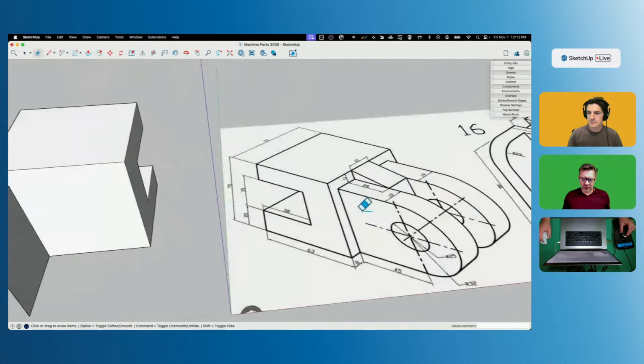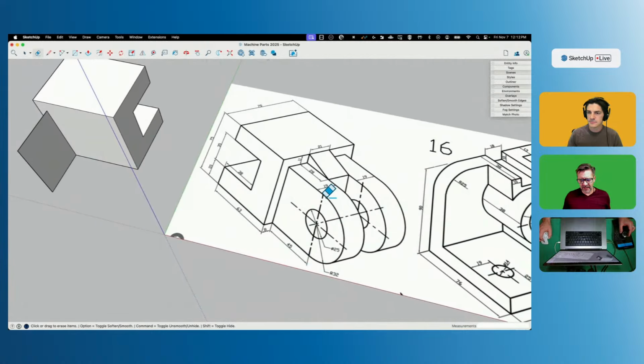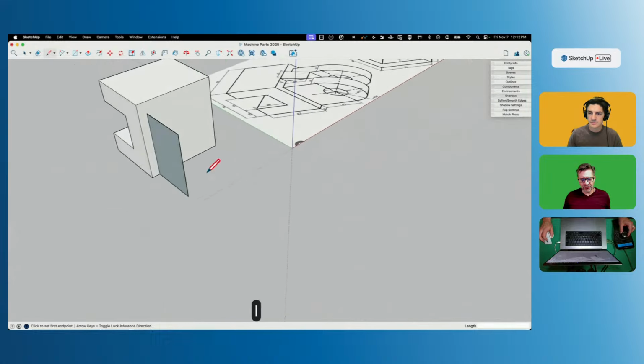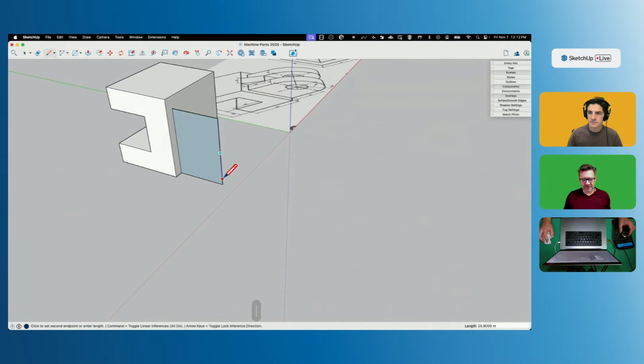So to put this round portion right here, to have a radius of 32, so that should be half of this. If I go to the middle here and pull this down, it is 32 right there. So I'm just going to grab a circle. I'm going to go to the middle. I'm going to put 48 in for my sides. And like I said, they'll all be that. And I'll pull that up like that. And there we go. So now I know that that's the same size.